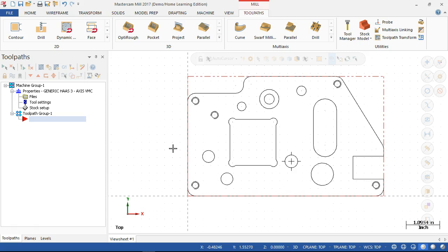And in this case, knowing that this is probably going to be on a plate, again, held down with clamps, and we have to manipulate, I would maybe put a clamp in the corners, run the pockets, and hopefully my tooling plate will show up with some other clamp locations on the interior.